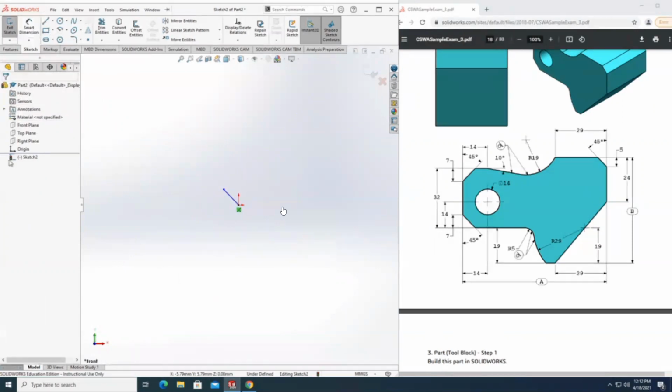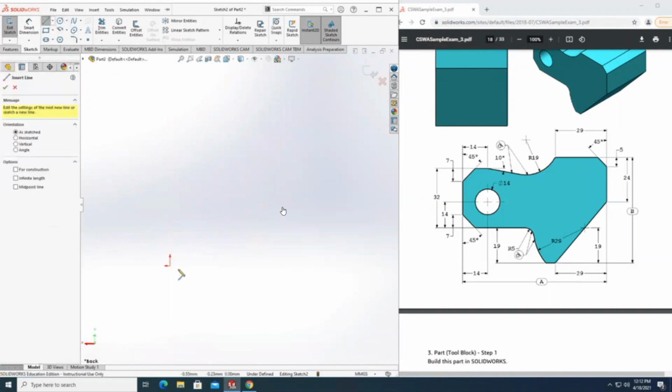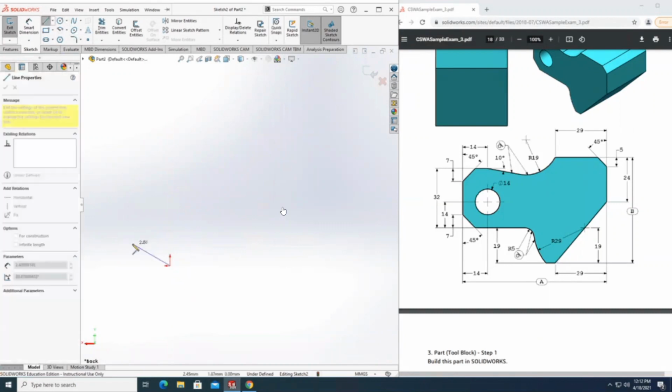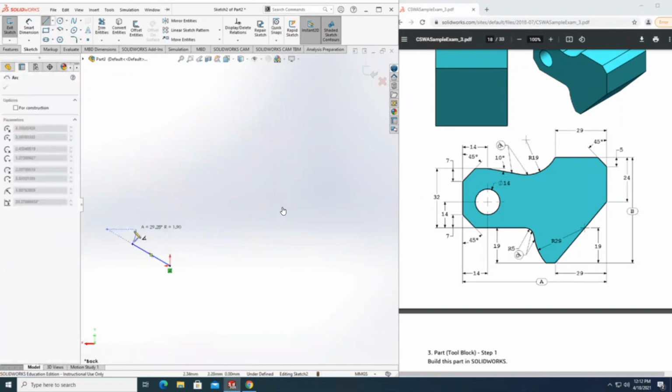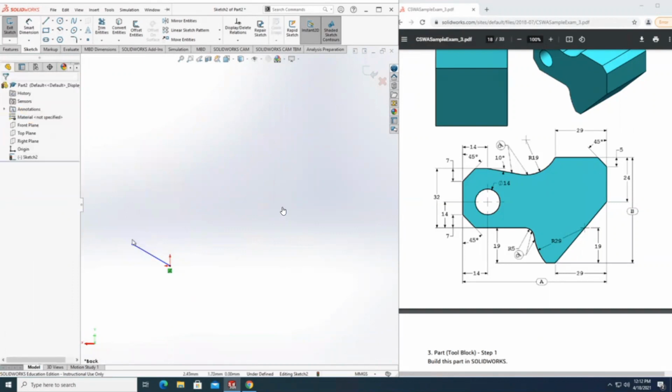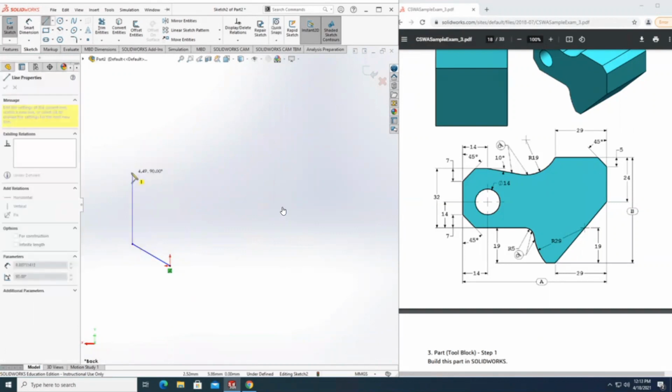So if I just go to normal view, yeah, that's why it was messing up. Give me 1 second. Let me go back. I'll delete this. So make sure you're always in the normal view of the sketch. It'll make things easier. So I'll start with making this one line and then making the general view.